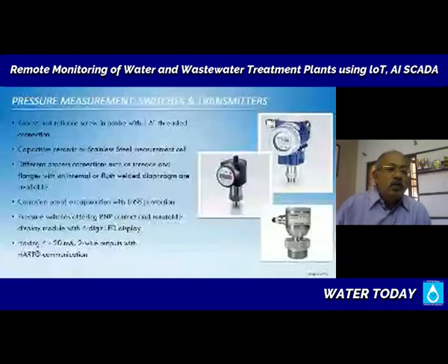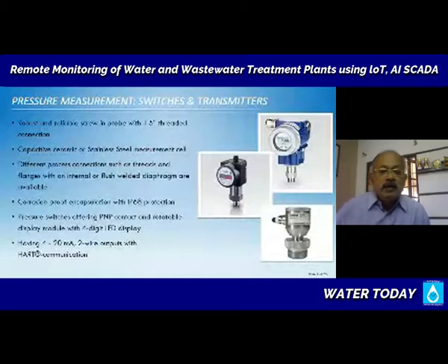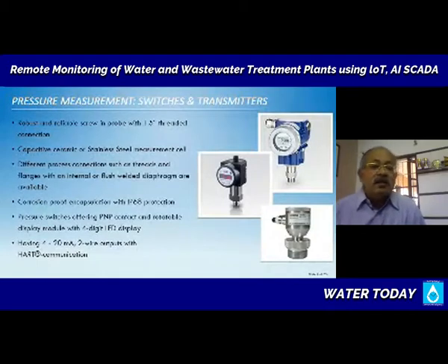So for this online, you can use pressure measurement in association with computerized systems like SCADA. You can measure the pressure and say this is 4 bars, 6 bars, 2 bars in a water network, and you can have a local display for any operator who would be passing by. You can also send a signal to a central control room using a very conventional method, the last item there, which says 4 to 20 milliamps, 2-wire output.